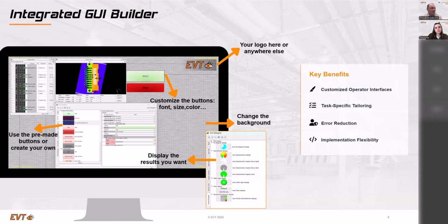And of course, you find all the communication tools inside. For example, OPC-UA, Profinet, Modbus, and whatever, to connect to the rest of the environment, to the machine, or to the SCADA system, where you have to send the data. And of course, you also have direct access to the I/O hardware. If, for example, you have only a smart camera with maybe some I/Os, you can directly control these I/Os with the graphical interface. So no need to do the programming.